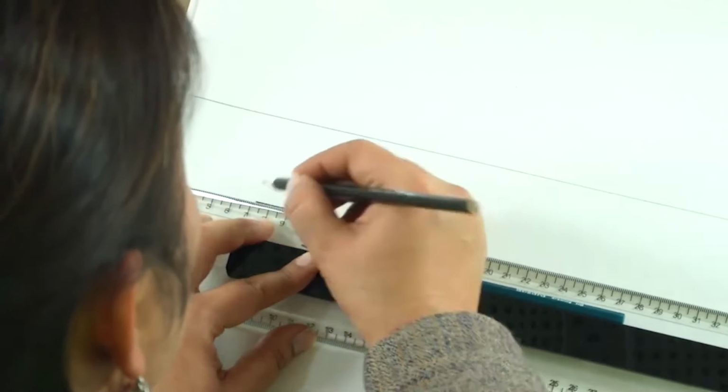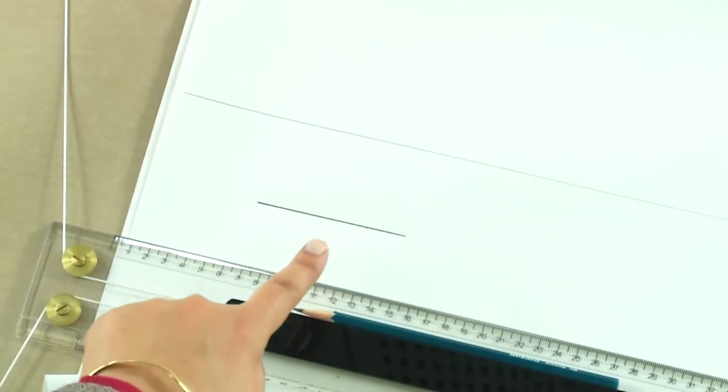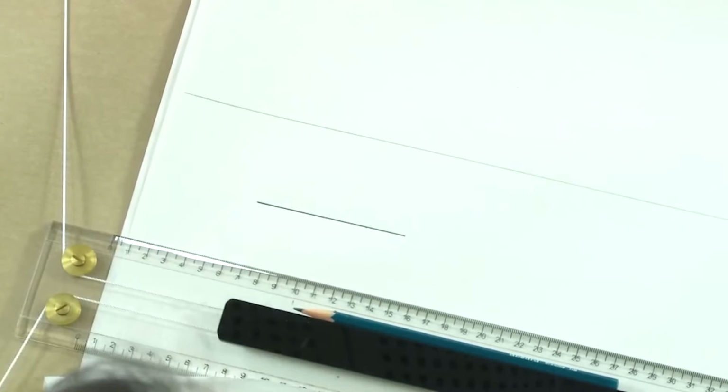We should always be careful about the thicknesses of the lines that we are going to be using. So, for darkening, I have used a 2B pencil. Ideally, we should not be darkening directly. You should always draw the entire drawing in light pencil, say 2H first. This is 2H in my hand.